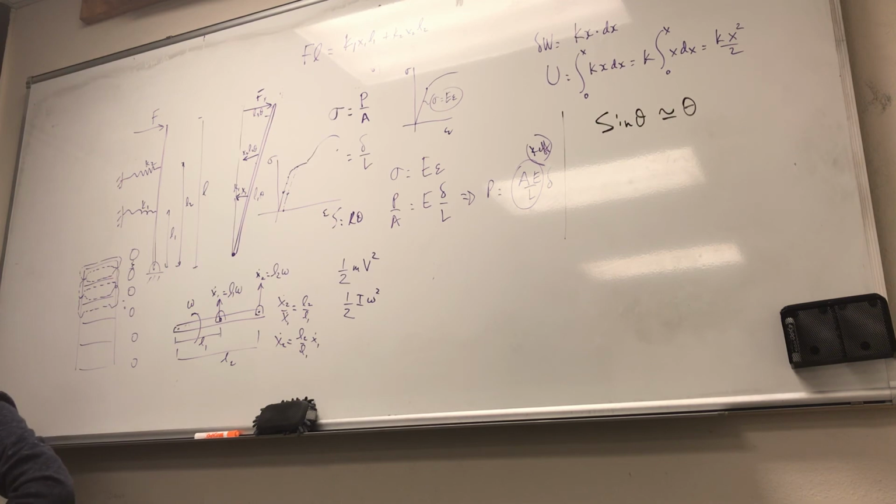So when you look at this, the energy contained within this curve is actually the amount of energy that you are typically losing through each cycle. Because the energy, if you recall from strength of material, the energy expended per unit volume is simply the integral of sigma d epsilon, which represents just the area under the curve.